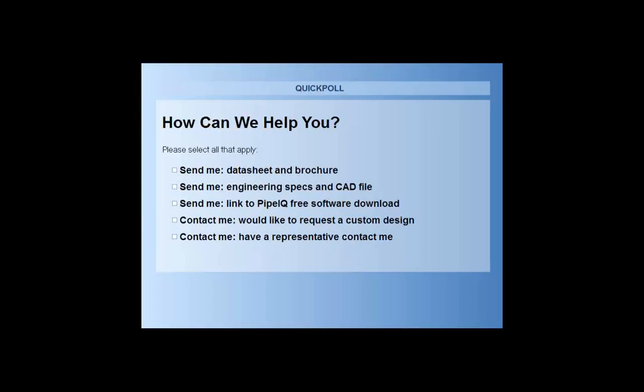Guys are wondering about the total length permitted for one system. I believe they're talking about the total length of pipe. Right. The total aggregate amount of pipe is 328 feet. That's for a branch system, and the total amount for a single pipe run, so one straight pipe, is 262 feet. Okay. They're wondering about the software.